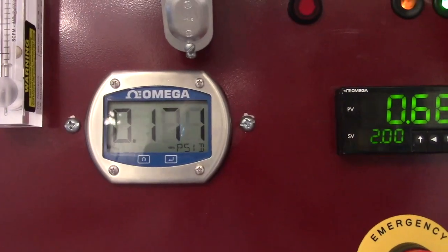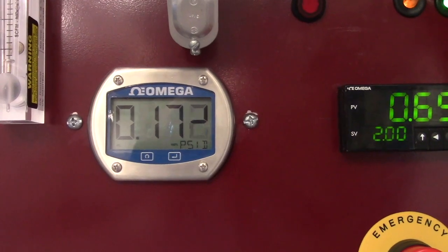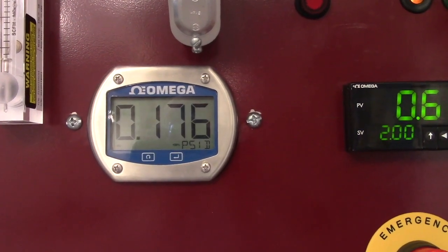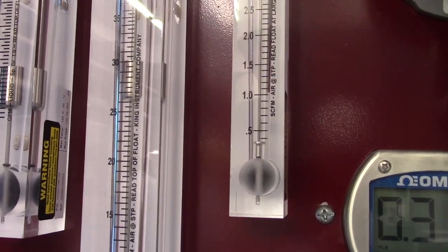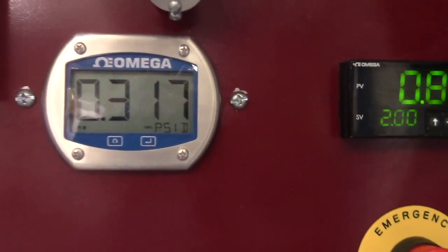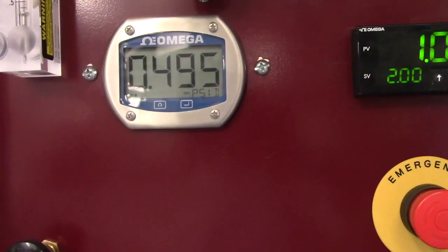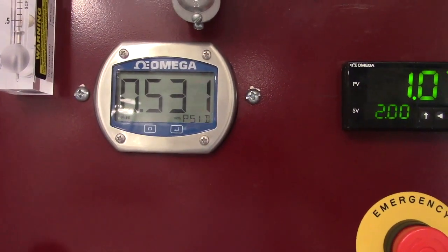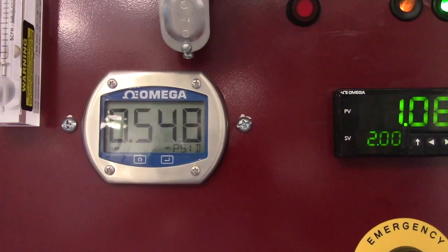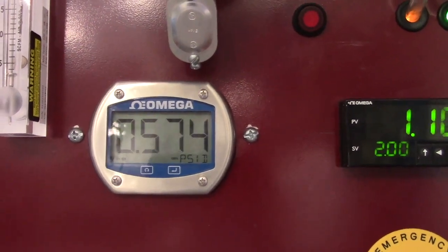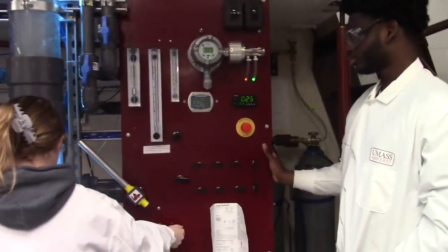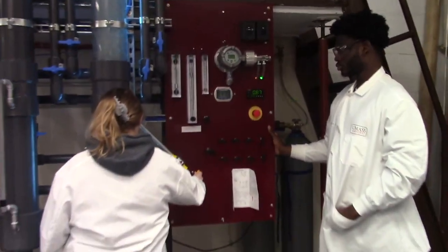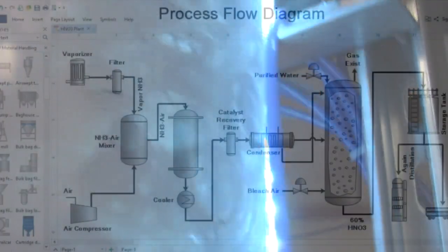We can monitor the pressure change between the top and the bottom of the column. Since we have both fluids flowing and we increase the gas flow, the pressure drop between the top and bottom will increase, and as long as we have not reached flooding, it will remain relatively stable at its new value. However, if we have reached flooding conditions, the pressure drop value will not stabilize and it will start to quickly climb. Once again, our group collected data, this time without the help of a computer, in order to determine ideal operating conditions for the columns at different liquid flow rates.